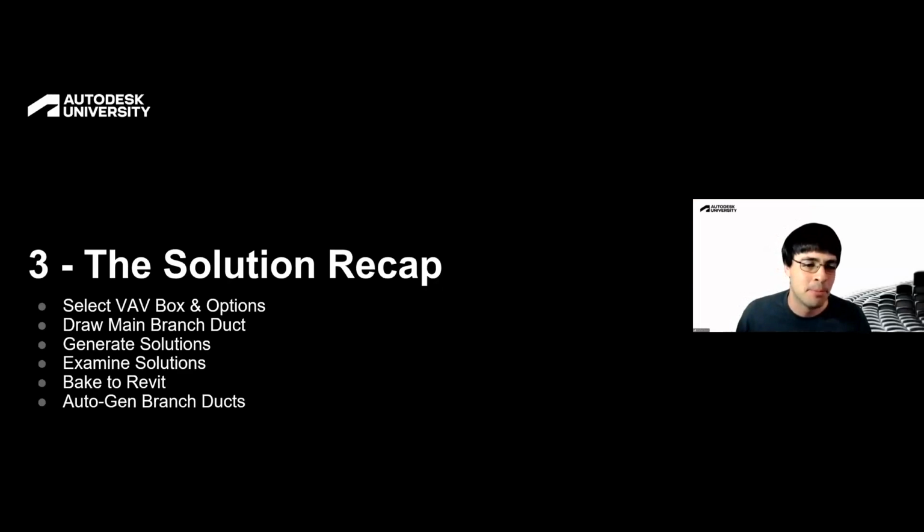Okay, so to recap, we built this Revit add-in where you select a VAV box and options, draw your main duct branch, and then generate solutions. Examine those solutions, pick the one you like, and bake it to Revit. And then if you're brave enough, you can hit that auto gen button, see what happens.